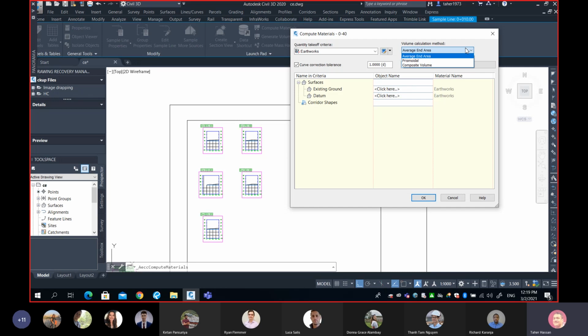Did you guys learn in my class about the prismoidal method? Yes. Okay, did you also learn in my class about average end area? I know prismoidal and I know trapezoidal. I already mentioned sometime in my class that trapezoidal is simply an average end area, because the trapezoidal method does nothing more than estimating the end areas, getting the average, and multiplying by the distance, but it does it on a quick basis.